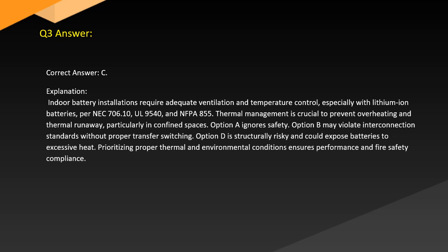Option A ignores safety. Option B may violate interconnection standards without proper transfer switching. Option D is structurally risky and could expose batteries to excessive heat. Prioritizing proper thermal and environmental conditions ensures performance and fire safety compliance.